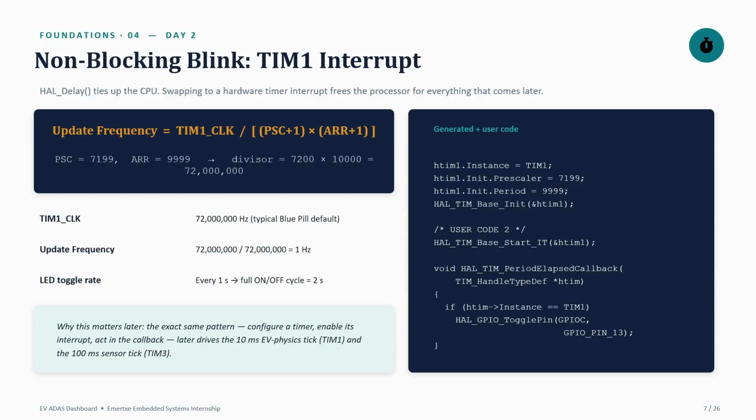The timer interrupt plays an important role because the hard delay of the blocking statement is entirely on the CPU while it's performing some operations. The single LED blinking becomes a bottleneck for other processes, like reading the sensors or running the physics calculation at the same time in the background.